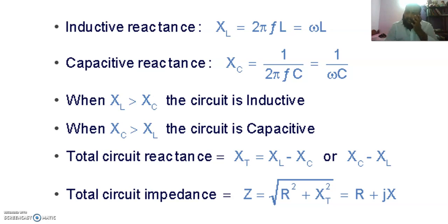So saying about the inductance, the inductive reactance can be referred as XL is equal to 2 pi FL. So next we are saying about the capacitance, the reactance will be XC equal to 1 by 2 pi FC. So both inductor and capacitor create a reactance, that is storage effect. Since it is in series, they will cancel each other.